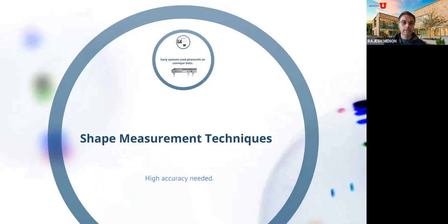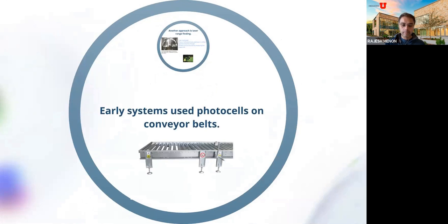And one of the first solutions people did was a very simple system where they had a simple conveyor belt, and they had a laser, which you can see right there, and then they have a detector. The laser is standing up there, and there's usually a detector on the other side, which you can't see in this picture, but the laser illuminates the detector. So this is the laser, and this is the detector. And when this path is blocked by a bottle, right? So at one instant of time, it goes down on the conveyor belt and it blocks the light. The signal is blocked, so you don't see it, right? You see a blip, a drop in the signal.